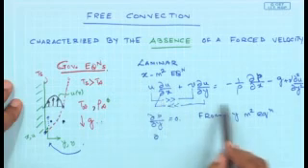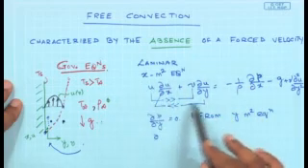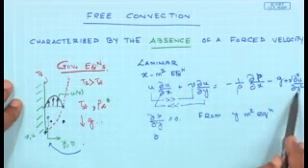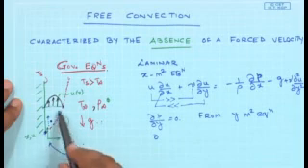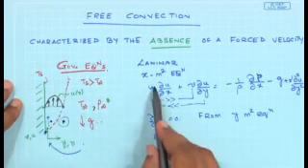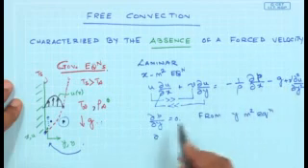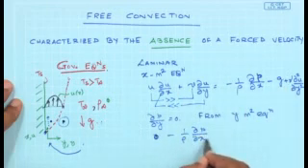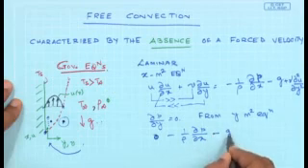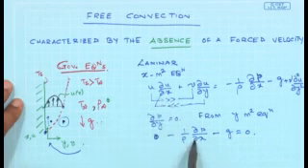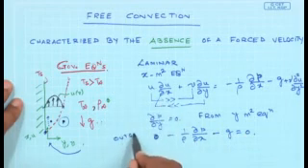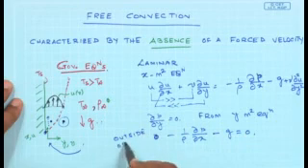So the equation that I have written over here, the x component of the momentum equation, if I write it for a region outside of the thermal boundary layer, then all these terms would be 0 except -(1/ρ) ∂p/∂x - g = 0. So that's the form of the equation if I write it outside of the layer.